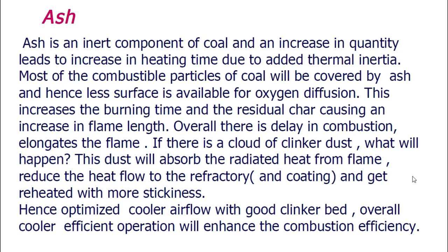If there is a cloud of clinker dust, what will happen? This dust will absorb the radiated heat from the flame, reduce the heat flow to the refractory, and get reheated with more stickiness. Hence, optimized cooler airflow with a good clinker bed and overall cooler efficiency operation will enhance the combustion efficiency.